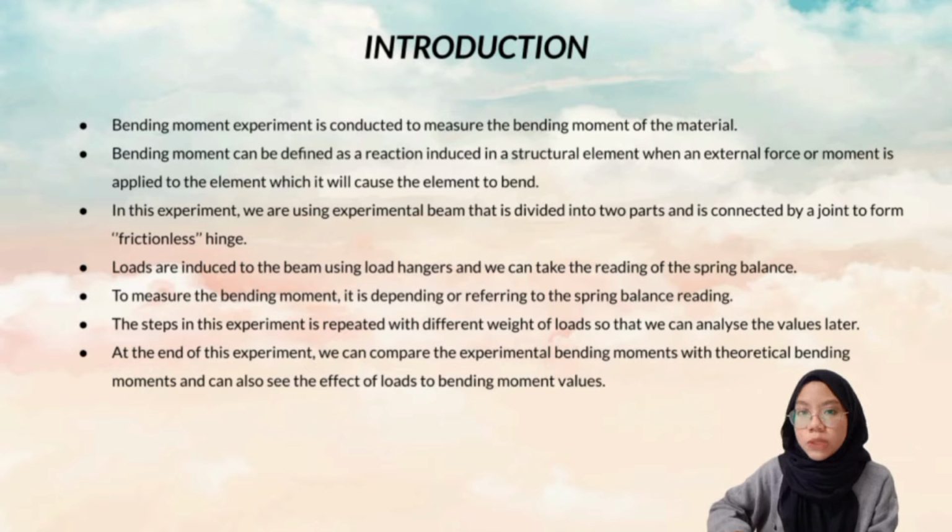So in order for us to measure the bending moment, we need to depend on the value of the spring balance reading. The steps in this experiment will be repeated by using different weights of loads so that we can analyze the different values given by the spring balance later. So at the end of this experiment, we can compare the experimental bending moment with the theoretical bending moment, and also we can see the effect of loads towards the bending moment values.